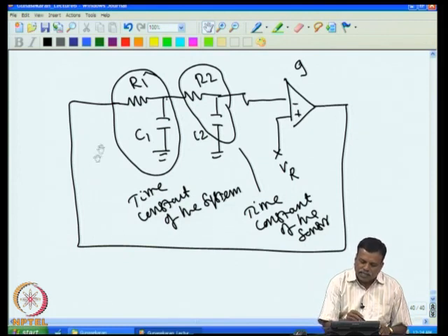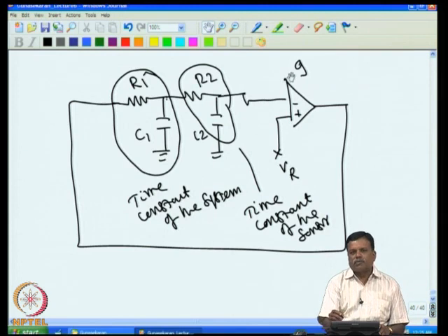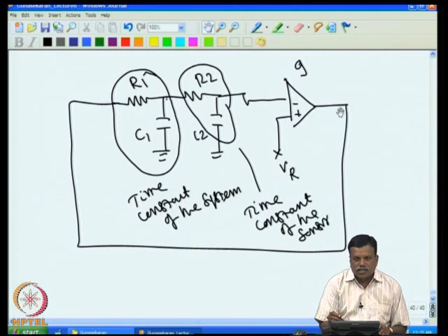Now if I have a system like this, naturally it will oscillate, because if I increase this, the increase takes place with a time delay, and even the voltage in the oven is sensed only after again some time delay given by the sensor. Because of that, by the time it reaches the actual temperature, the voltage here has already gone much higher, and the net result is the system will keep oscillating many times. Now if the gain is sufficiently large here, of course, if the gain is less, it will not oscillate.